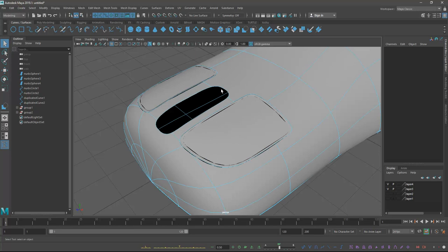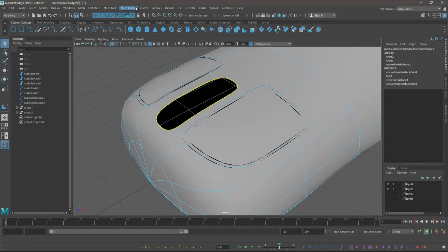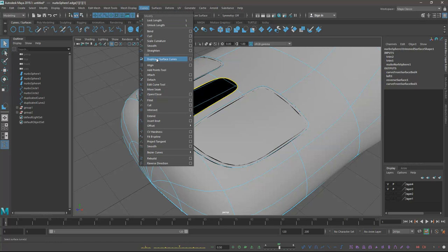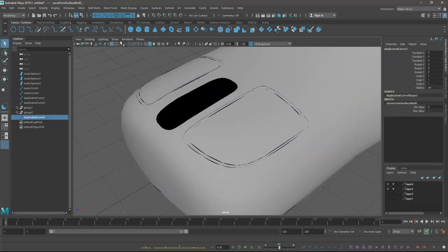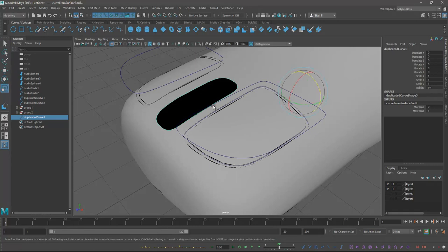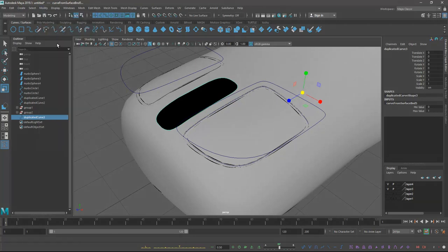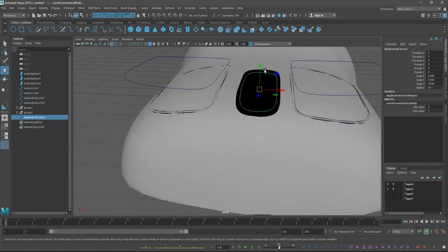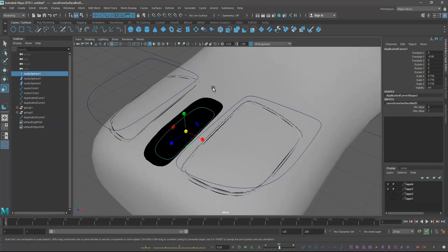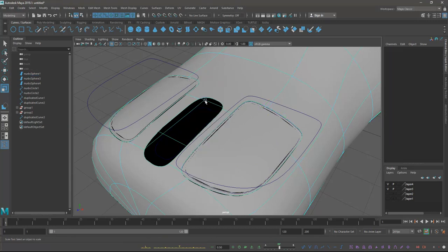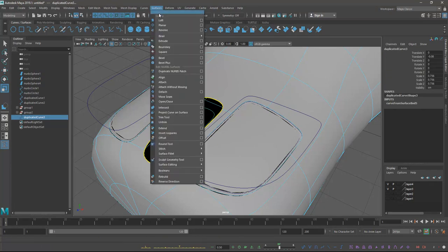The same way I'm doing here. So again trim edge. So the trim edge, again go to curves, duplicate surface curve, and enable, and modify center pivot, and keep it a little down like this, and again trim edge, and shift select the curve, and again surface and loft.